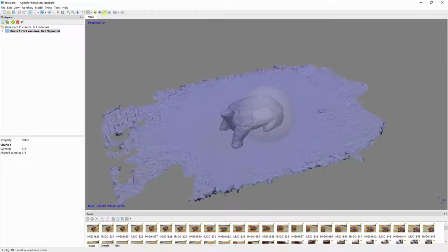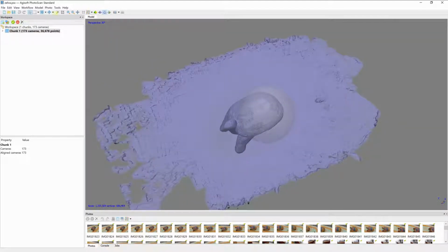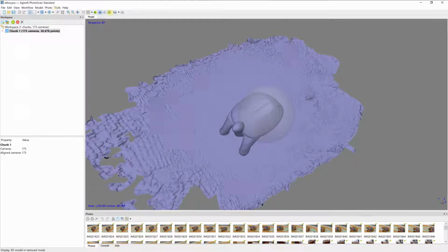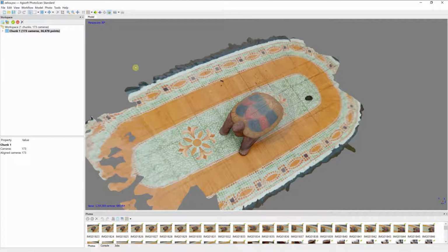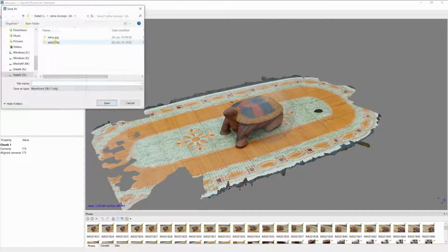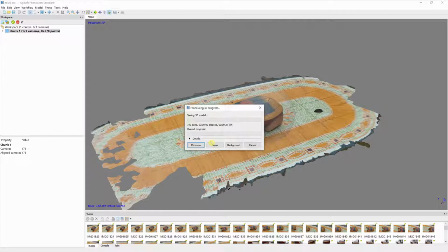This means with the picture on it. If I make it like this, now we see just the wire mesh, and now we see the faces of the 3D model. So it looks good. We can export. We go now back here, and we shall export this as an object file, as a model. We go to File, Export, and Export Model, and we write here turtle object. Okay, save. Wait a little.